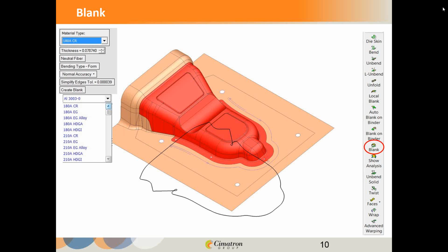It will make a huge difference, as you know. Stainless steel is not going to react the same as mild steel. And there are some steels out there now with a hardness to it that rivals the hardness of the die steel that's forming it. So it makes a huge, huge difference to be able to select the right material, not to rely on just mild steel all the time if it's a different type of part.